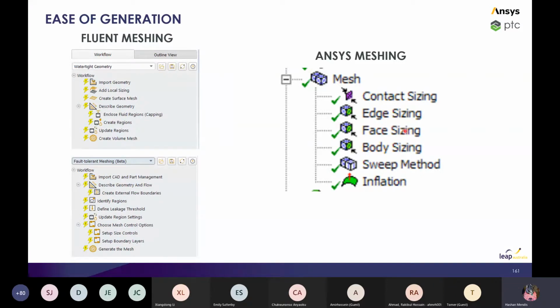So in both these settings, and we'll have a look through them a little bit later on, under the mesh we've got all these different conditions and components that have been created, giving us information about things like the edge sizing, body sizing, how we've actually generated this mesh. It allows us to regenerate the mesh easily based off features and name selection as well.